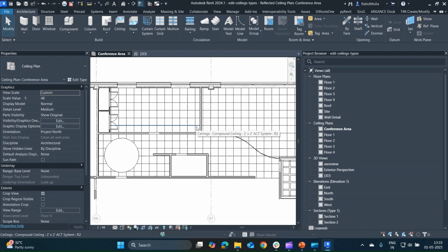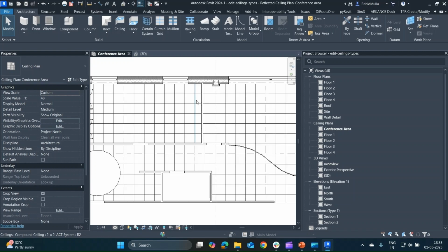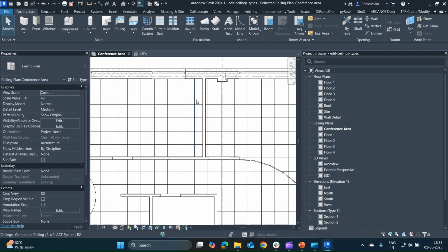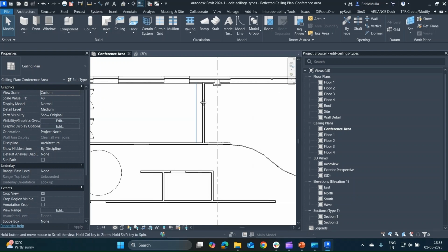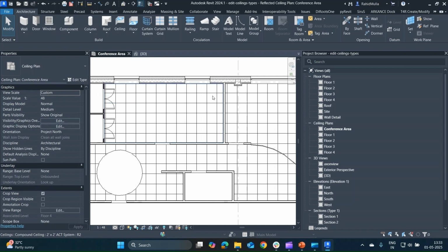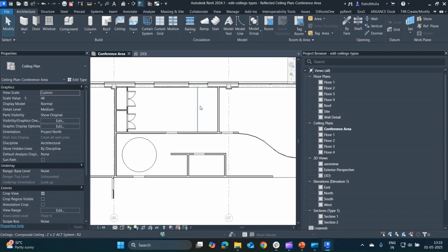Set out point for the ceiling, so that when workers are there, they get a clear idea how to place or how to keep these ceilings in respective sizes. So when the drawings go on site, here we will give this as a balance option, mentioning that it has to be balanced with respect to the site condition. Here as well it has to be balanced with respect to site condition, and in between everywhere there will be a dimension specified as 2 feet.